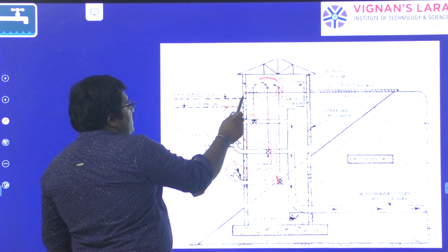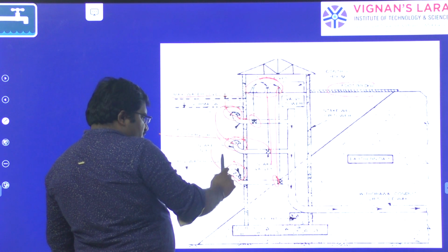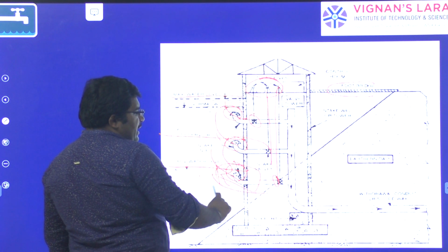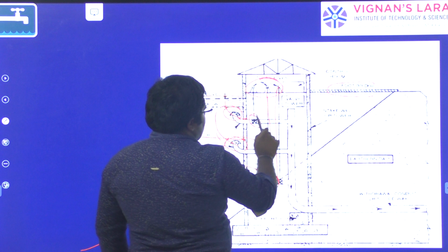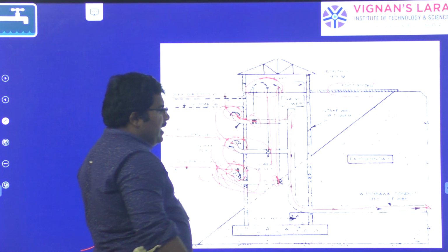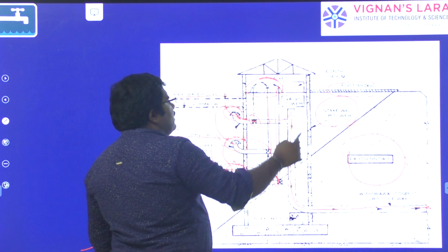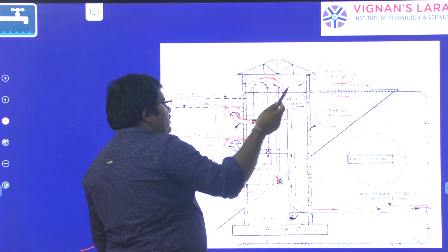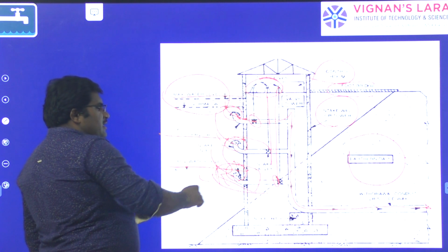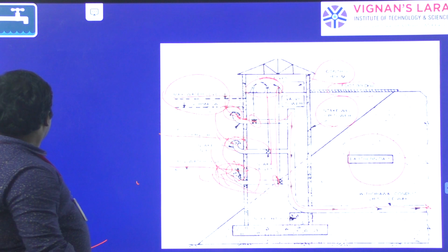Okay. If maximum water is there, the water will be collected here also. As the water is reduced, only two will collect. If fully reduced, only one pipe will collect the water, right? So all water will be taken in a common pipe and taken out of the dam, right? So this is the earthen dam, and this is called intake well or tower. This is the control room where we have pipes and other things. Okay, this is the maximum water level or normal water level. This thing is called reservoir. Okay, so these are the parts of reservoir intake.